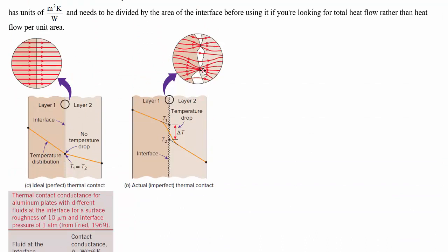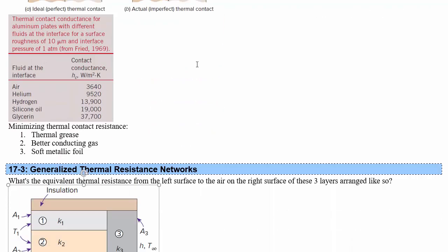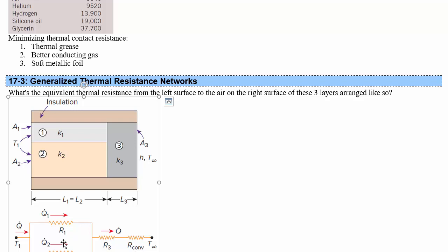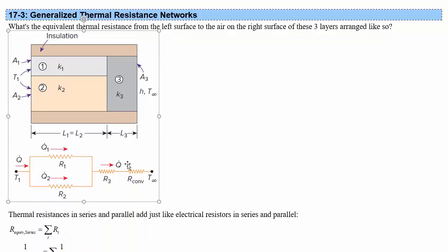If you have one section that's easier to flow through, then the streamlines would condense on the way towards it and then spill out after that. But to do this assumption is to assume that heat can flow perfectly in the perpendicular direction to the heat flow, so that these cross sections are sort of isothermal, and that's not really perfect.